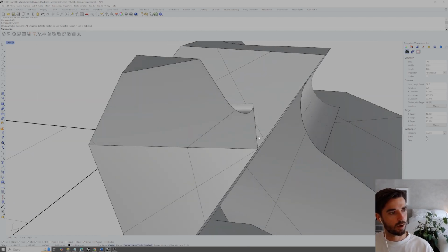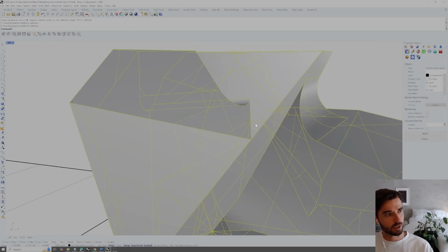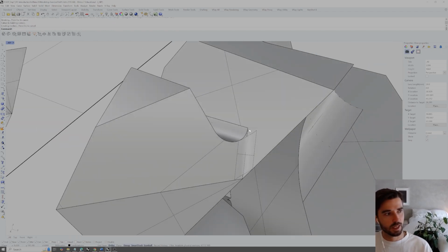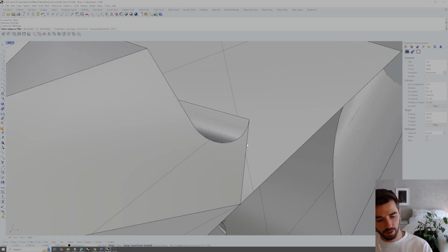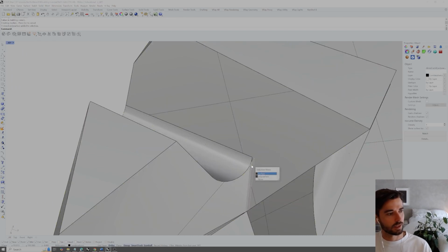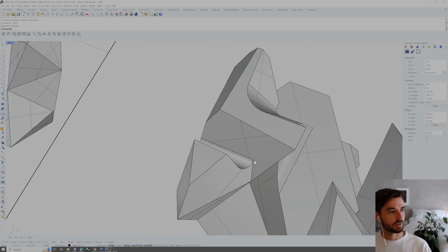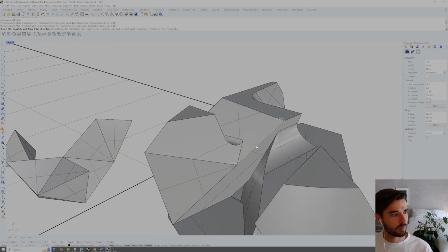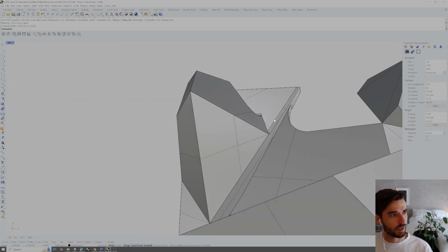If you wanted to now, after you've made those adjustments, you can also go in and try to fillet the edge to even make that transition a little bit smoother. You can go ahead and try and see what it gives us. So it is having an issue with that. You can try a slightly lower radius. It still seems to be having quite a tough time with that area. I think there's just too many junctures. Let's try maybe that.